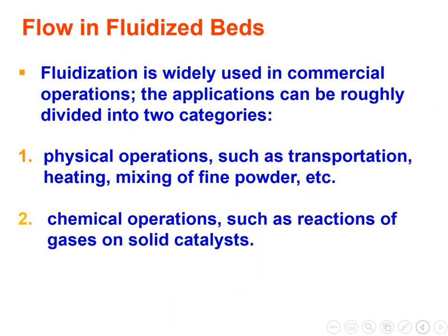So where do we apply fluidization? Fluidization is widely used in commercial operations. The applications can be roughly divided into two categories. There are a lot of applications, but we can have physical operations such as transportation. As I have just said, in the pneumatic transport, I can apply high pressure, where the particulates will transport from one place to the other. I can heat them, I can mix the fine powder, etc. All of those are physical operations. I don't have any chemical reactions.